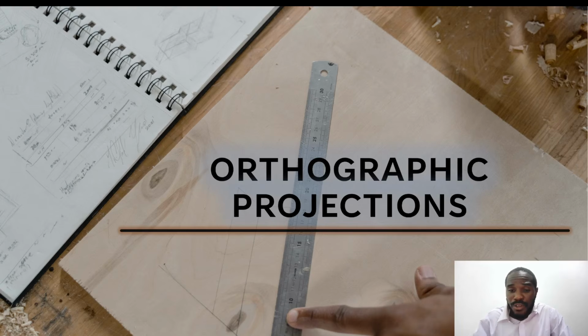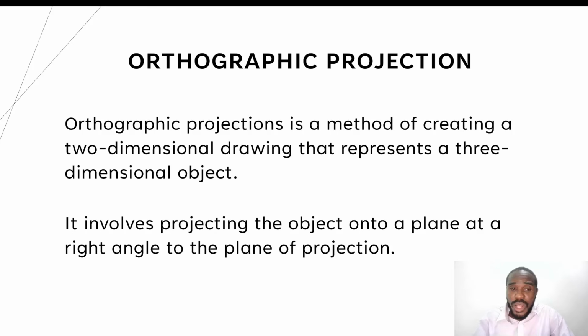And orthographic means at 90 degrees too, okay? So when we talk about orthographic projections, we are referring to a method, a way of creating a two-dimensional drawing that represents a three-dimensional object. Okay. Now we've just seen techniques that can be used to add depth to a drawing to show that it is three-dimensional.